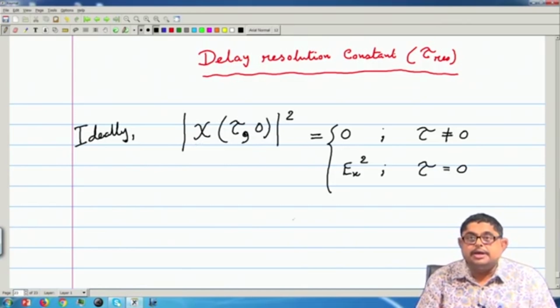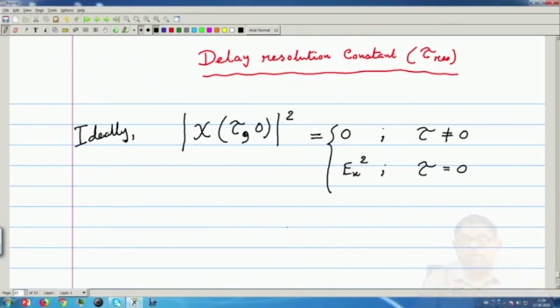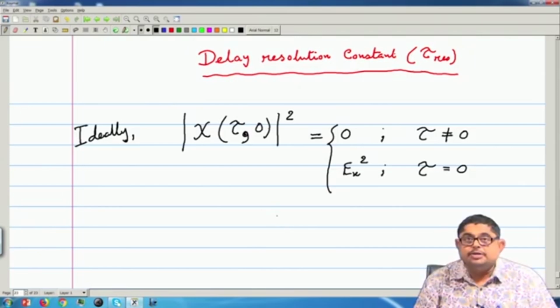And we know that the range ambiguity function is nothing but the autocorrelation of the transmitted pulse. So, what we are saying is we will have to transmit an impulse type or very short pulse, covering the entire energy, but this is impractical because it will limit the transmission capability, because every transmitter has a power handling capability.